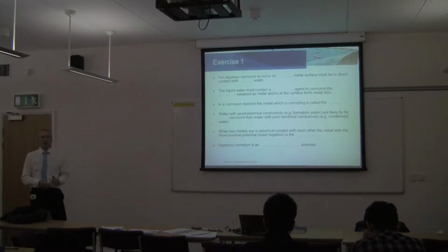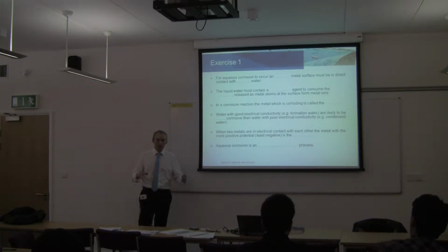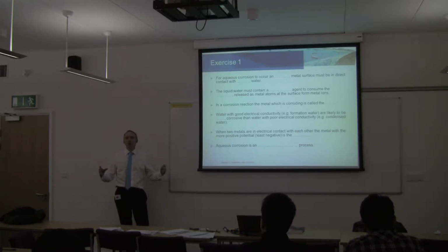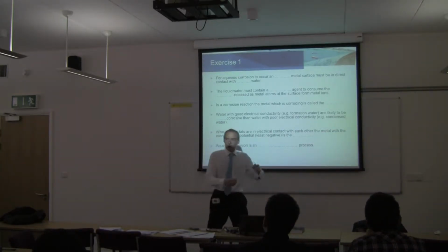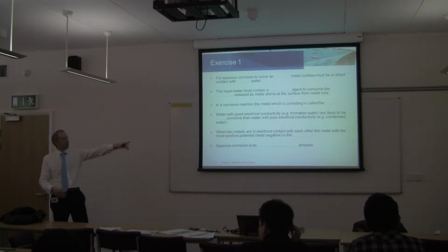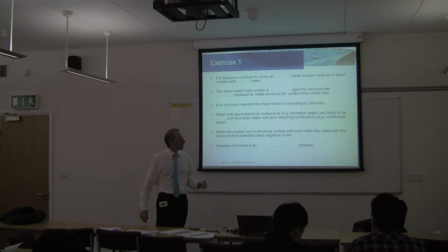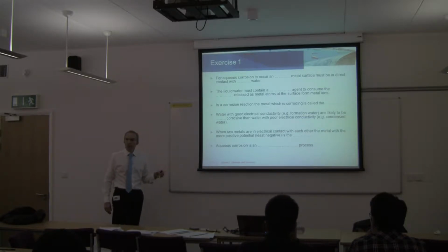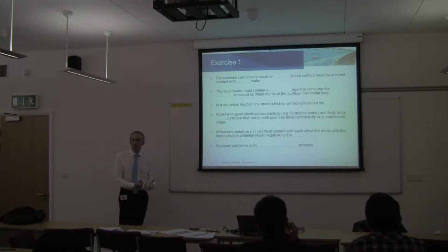Before we stop, just for a break there, I was asked about heat and corrosion, and I think the best example that we could give you right now is if you take a stainless steel pipeline and the passive film inside the pipeline is damaged for whatever reason, the corrosion products, usually chlorides, would attack the hole where the film is broken and then just drill down into the pipeline, and then once it's inside, it will start to eat away at the microstructure of the steel, and it will keep going. It's probably one of the most aggressive and dangerous forms of corrosion because it's not easily detectable until you've got such a large hole that it's basically punctured right through.